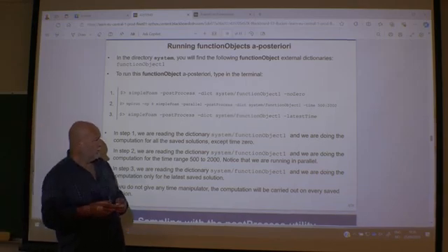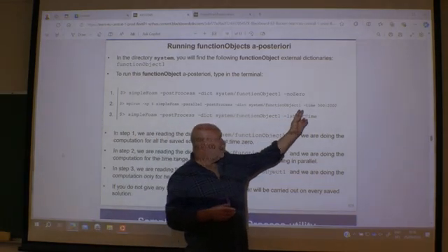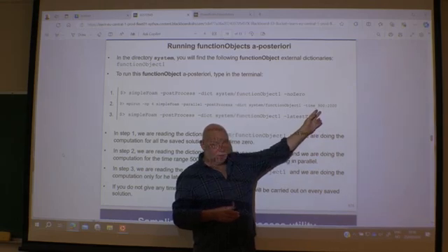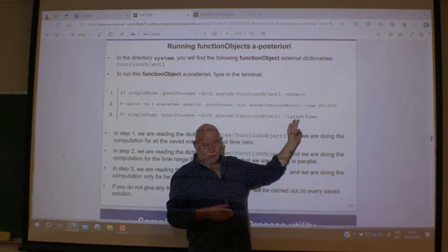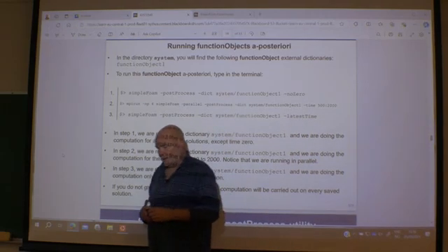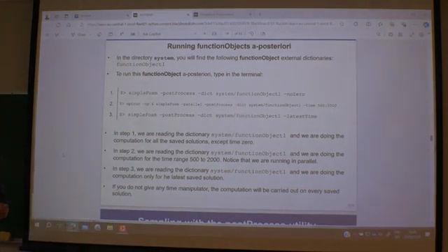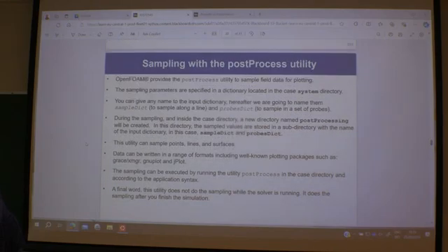And if you don't specify either some time limits here, some time folder names, or just the latest time, if you don't specify anything, he will do it on all the result folders that he can find. So your choice. Frequently we are only interested in the last one, but never mind. Sometimes you need all of them.